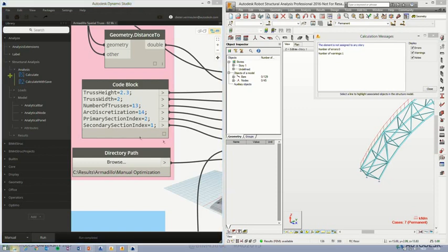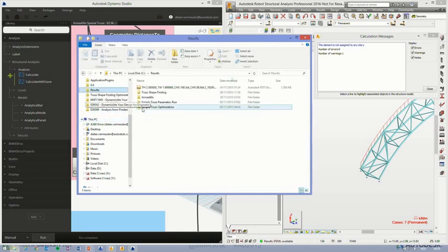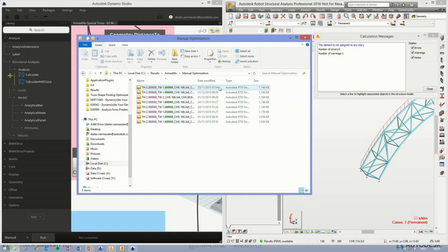Which means I will bring in that Dynamo script, add some specific nodes to reuse the values and to change the values manually. So I won't let the computer interfere in that. I want to do it myself first. If that one works, then the one with the computer, with the generative design or the computational design, will work as well. So that's a very important rule to follow. Just first make your manual scripts before you go into optimization.